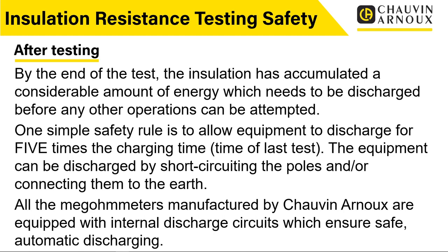Say you've locked the tester in the on position and you're moving the probe during the test sequence from conductor to conductor, obviously while the test is still live, it isn't discharging. So if you're moving from point to point carrying out that test, those items that you've touched are potentially still charged up until you discharge them. It'll only discharge when you finally stop the test and stop the test button. It'll discharge whatever it's connected to.